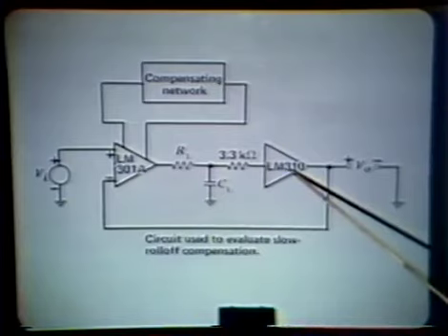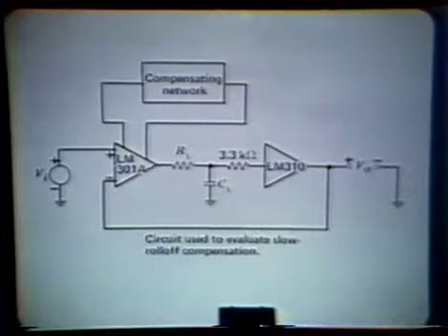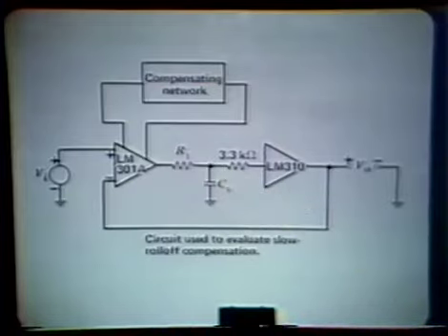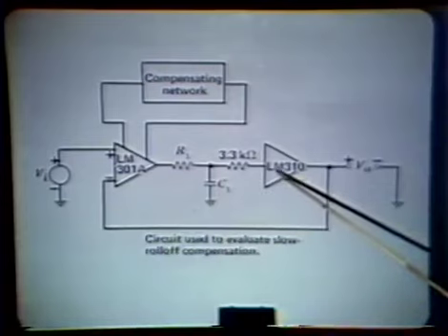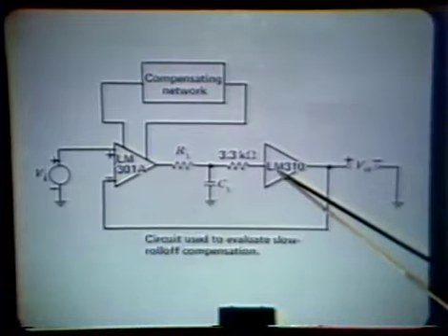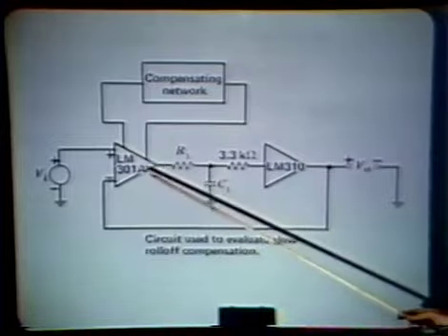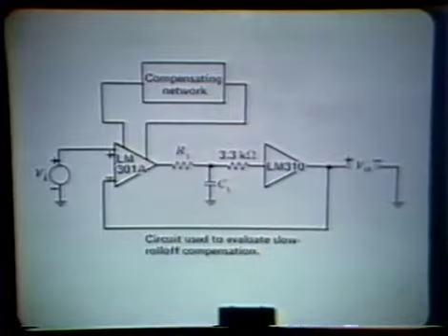We then have a buffer amplifier, a little unity gain follower that has a bandwidth much, much greater than the actual operational amplifier we're using, and we just use this to prevent any loading on the RC network, a little resistor that's recommended by the manufacturer when one uses this amplifier. And then we close the overall feedback loop. So the dynamics of this amplifier are such that it's basically transparent. Consequently, we have a loop transmission in this loop that's that of the operational amplifier times 1 over R1 C1 S plus 1, the low-pass characteristic of this network.